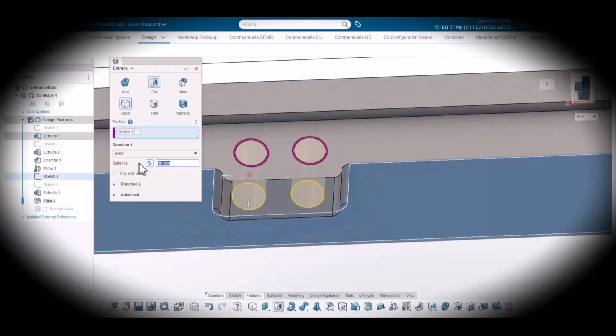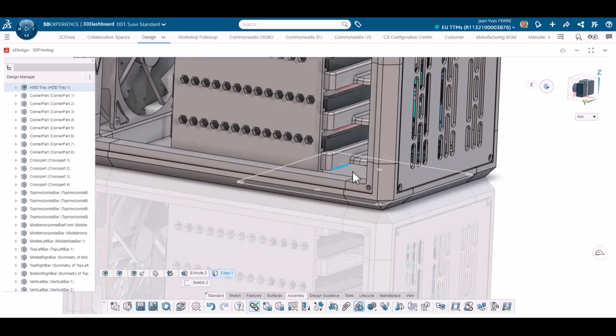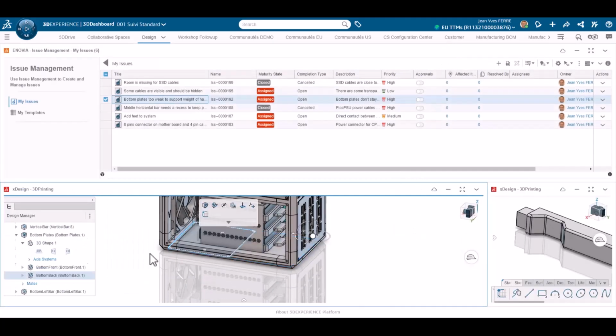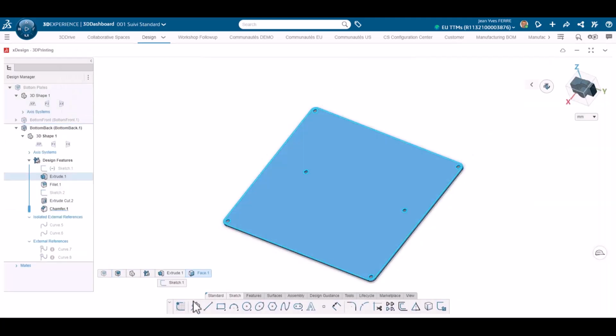With the former version, the bottom plates didn't look good, so I decided to first increase the number of mounting holes for the bottom plates, but it was still not strong enough. So this time I will increase strength, let's say, more seriously, starting with doubling the plate thickness. Then I measure clearance under the hard drives so I can build without risk.